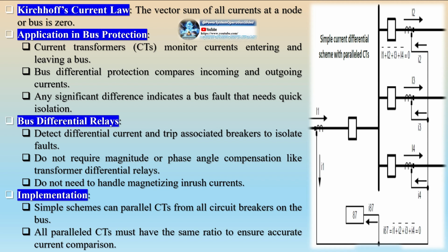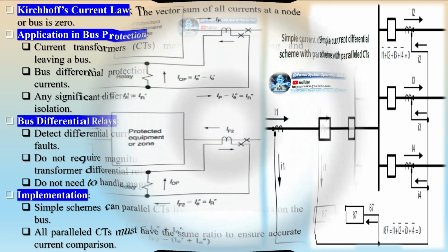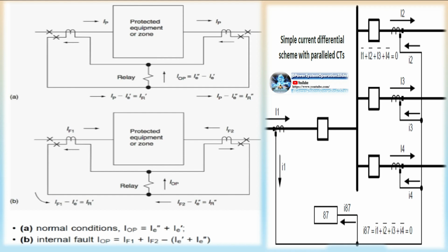Dead zone, blind spot. The section between the CT and CB is termed the dead zone. End fault protection is activated only when the CB is open. When the CB is closed, this function is not in play, allowing for a fast fault clarification. Faults in bus couplers. The presence of CTs on either side of bus sections and couplers is crucial for ensuring that faults can be detected and cleared. The strategy used can be selective or unselective, depending on the arrangement of the CTs.